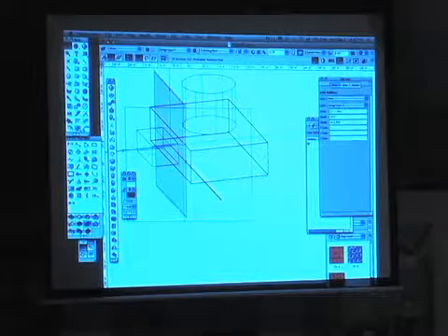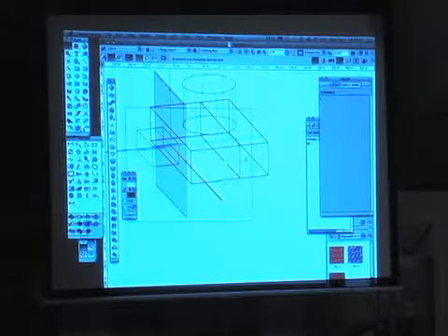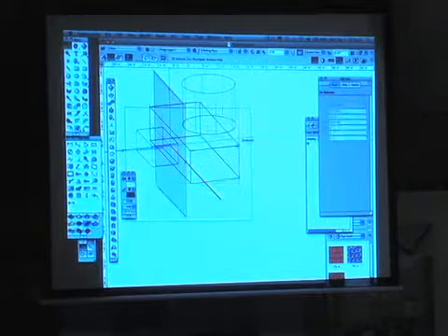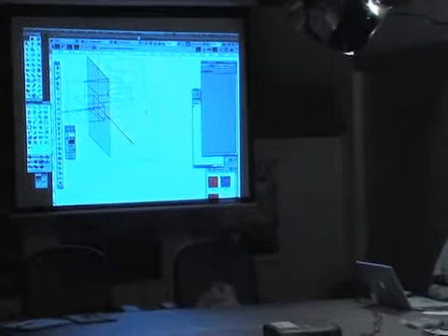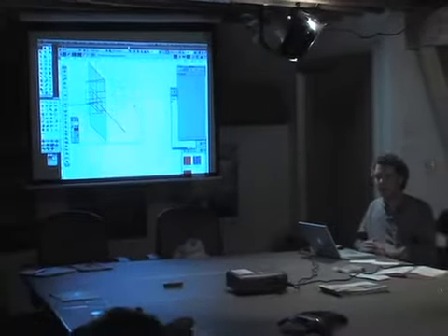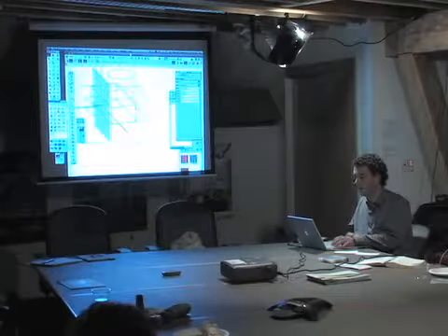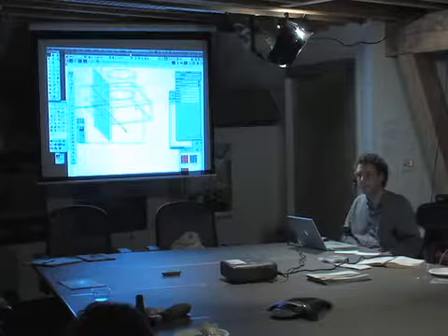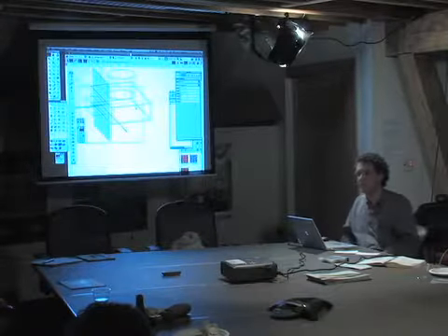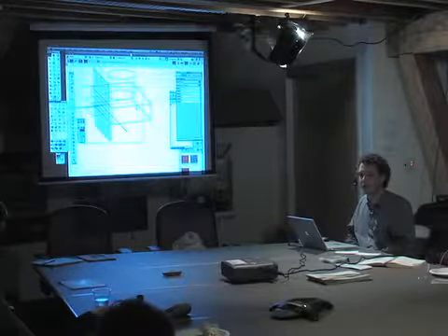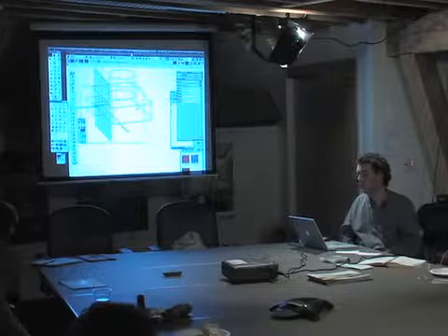Yes, that allows me to ungroup this and go back to my saved history. Before, if we wanted to add or subtract something, we'd have to do an add solid or subtract solid. So it still retains the different moves that we made. As long as it stays as a solid addition, some moves, when you do something, it turns to a generic solid, and you lose that ability to edit those steps that you took.